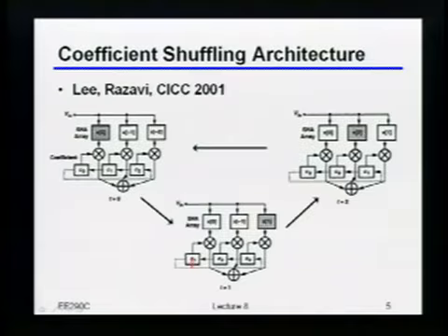Okay, and so you can imagine I can keep doing this rotation, and as long as I do the rotation correctly, and in this particular case I have to match the number of samplers to the number of coefficients, then I can build it so that I never have cascades of these sample and holds, right? Because notice I've always just sample and held once. I'm just feeding that sample and held value to a bunch of different multipliers. Okay? Does this make sense to people?